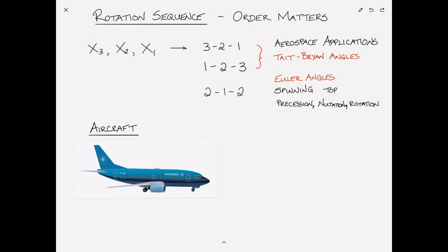And in various applications within and around aerospace, people have various ways of labeling their axes. Of course, up till now, we've always looked at beams, which could be wings, in which the x-axis typically runs along the elastic axis of the wing. However, when one looks at controls and dynamics of whole aircraft, typically the x-axis points through the nose, and the y-axis points down the right wing. And then, of course, because we want a right-handed set of coordinate systems, the z-axis will point vertically downwards.